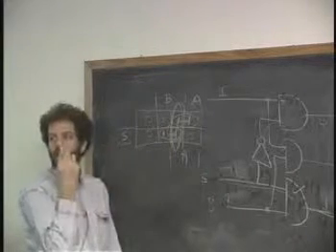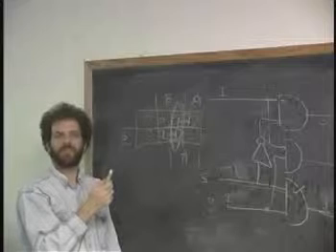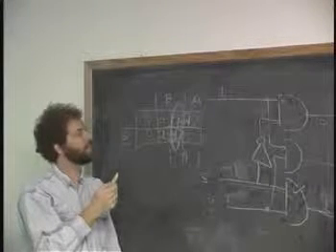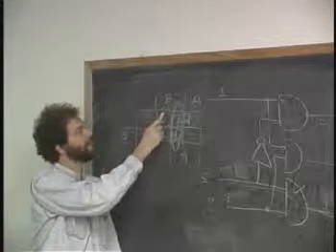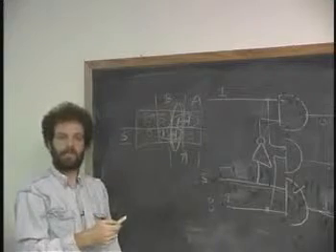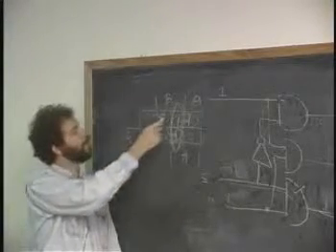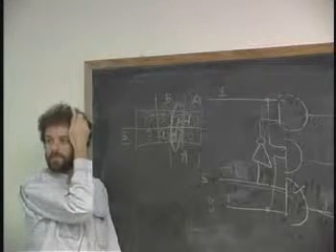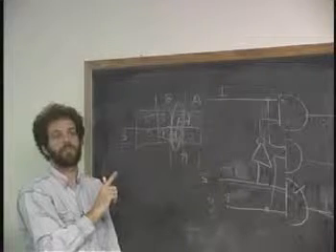But with that very same circuit, you could get a 0-0 hazard. Well, that's a good question. Can I get a 0-0 hazard? It's an excellent question. Let's say I'm here, and I translate to here. Well, 0 means I'm not on an island to begin with. None of the gates are going to fire. And now I go to another place where none of the gates are going to fire. And furthermore, only one input changes at a time.